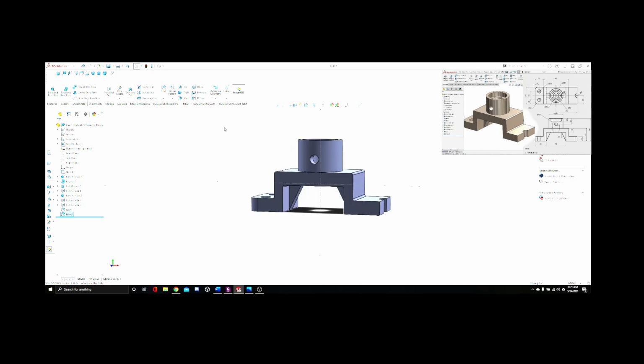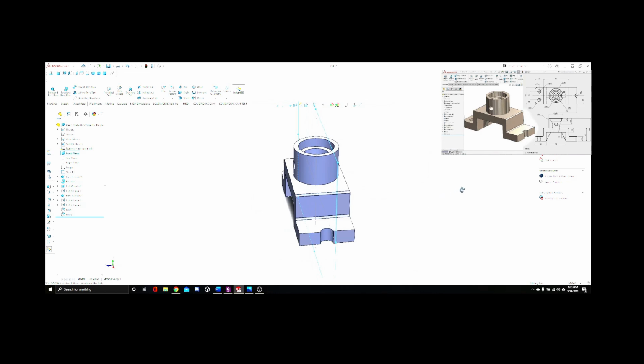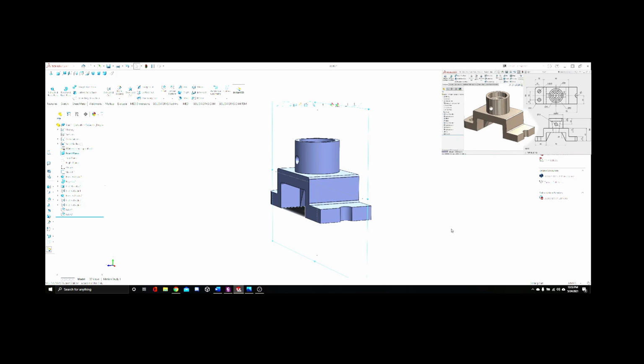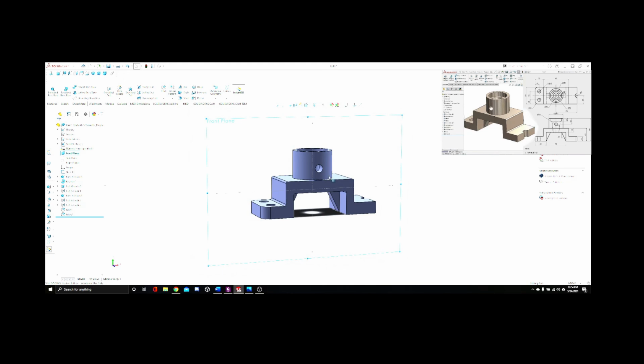Because it is centered around that plane, let's turn on that front plane and make it visible so you can see. It's bisected by that plane, so it makes sense to set your drawing up so that it's bisecting around that plane. And then you can put in your original reference lines and things like that to work off of. And the other thing with having it bisected around that plane and then centered around the origin is when we were drawing in these pieces, we're able to then mirror them around the base planes that are already set in the project.